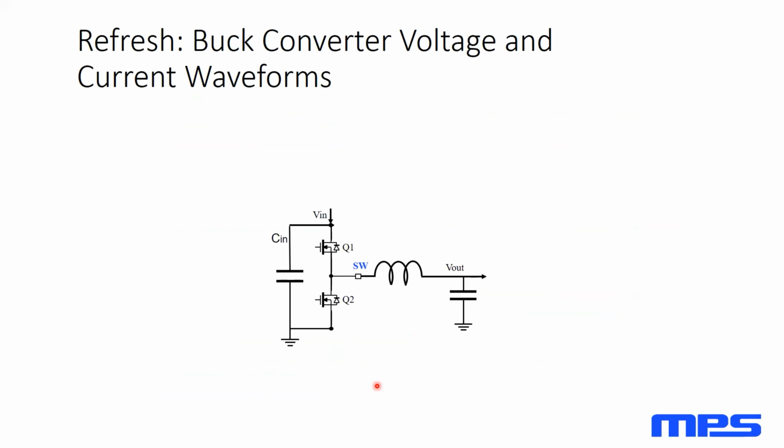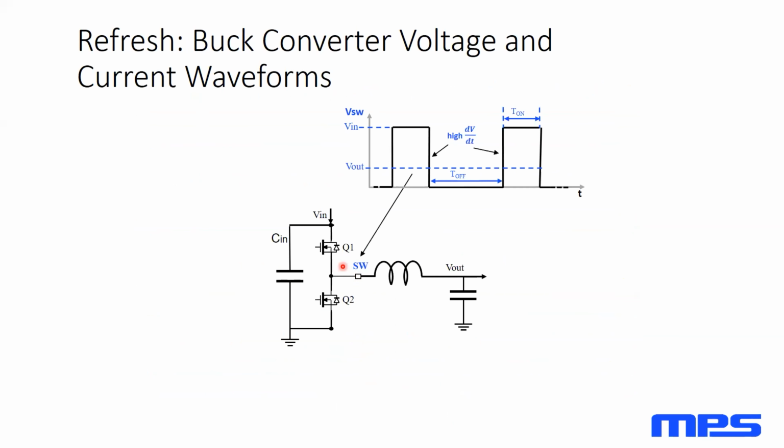So also going to take a look at the areas of interest for us. Francesca's touched on this a little bit. I'll show some of the waveforms. So from a buck converter, I'm showing the switch node here in blue, and we've got this high dV/dt, right? So from an off battery perspective in automotive, whether it's 12 volts or 48 volts or whatever the case may be, we've got that much voltage switching in a short amount of time, right? This dt is typically nanoseconds, and it's something we're going to trade off in EMC for efficiency, right?